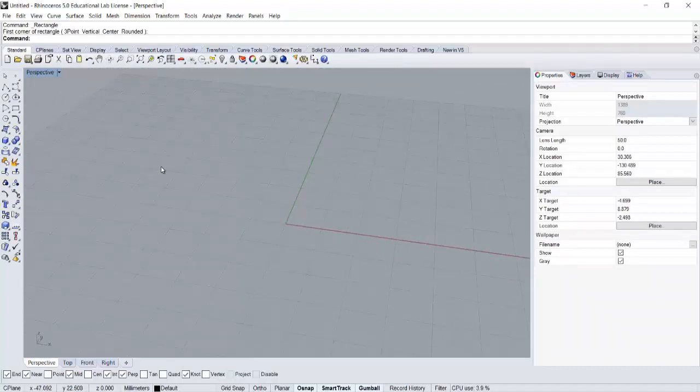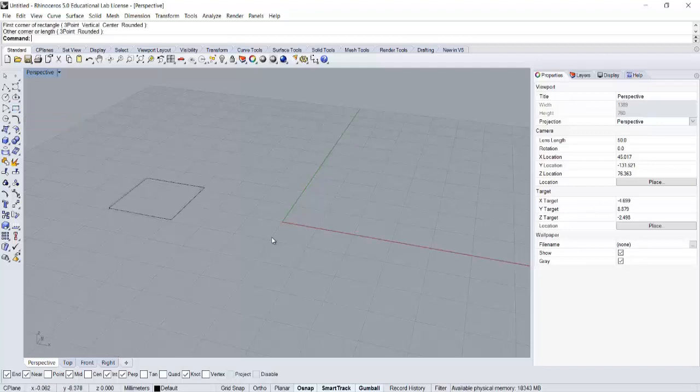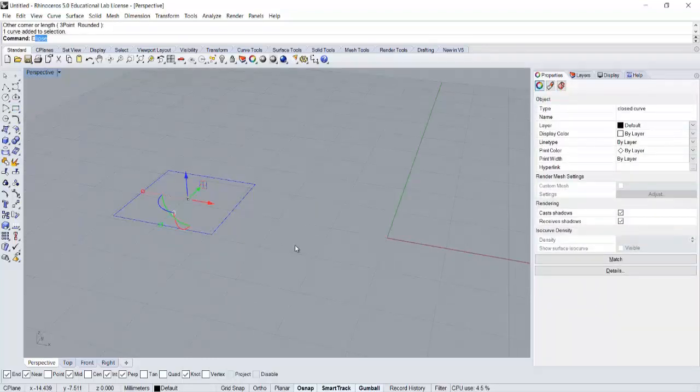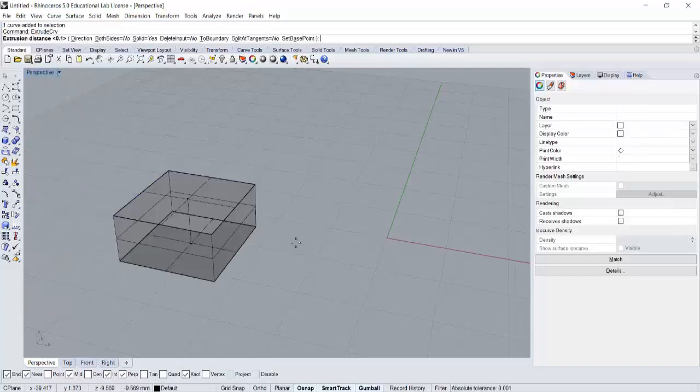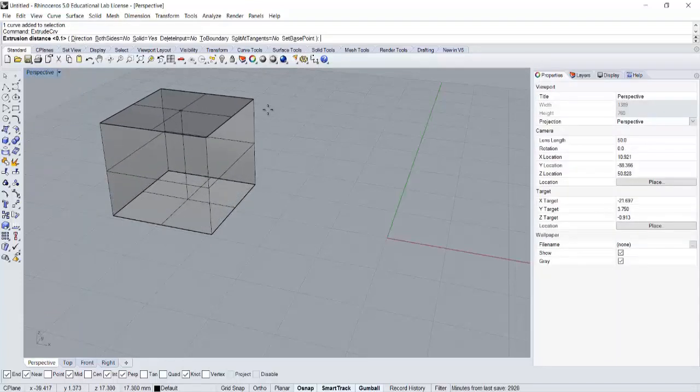One thing I like to reinforce when people are learning a three-dimensional CAD package is there are only a certain number of three-dimensional moves you can do, the basics anyway. So we'll work through them and you'll see them in lots of different softwares. So seeing beyond the software and more to the form that you're creating is what I'm trying to get you to see here. So for instance, if I take a two-dimensional curve and extrude that curve, I get a 3D object. But in the options in Rhino you get this here.